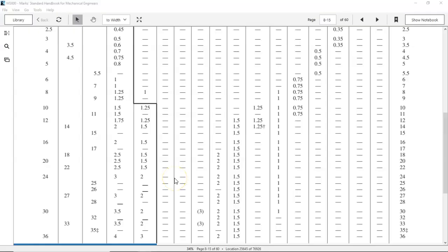So we've delved into the mysteries of the threads and all of the geometry that we're dealing with the inclined plane. And what that means for us in our mechanical design is we have a couple of options. In the video, I got ahead of myself a little bit and added the cosmetic thread, because we did an example with the 12, we did an example with the 10. And whatever we generate for the internal thread, we need to also make sure it aligns with the external.